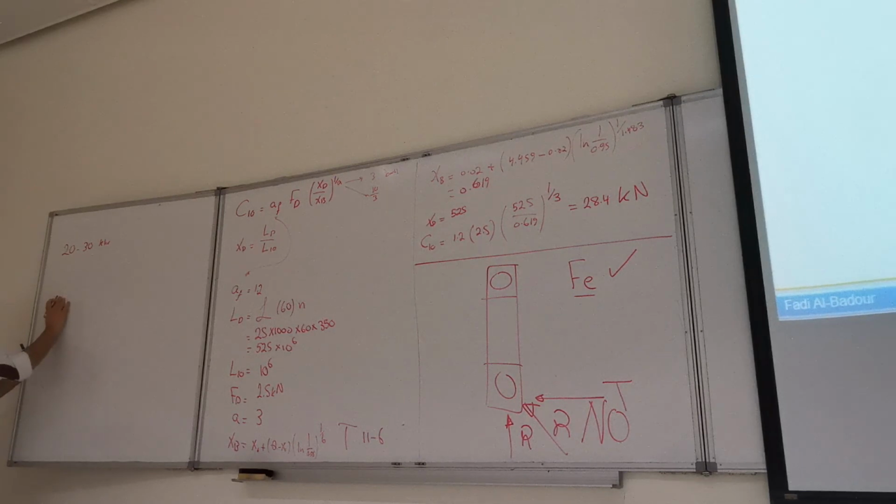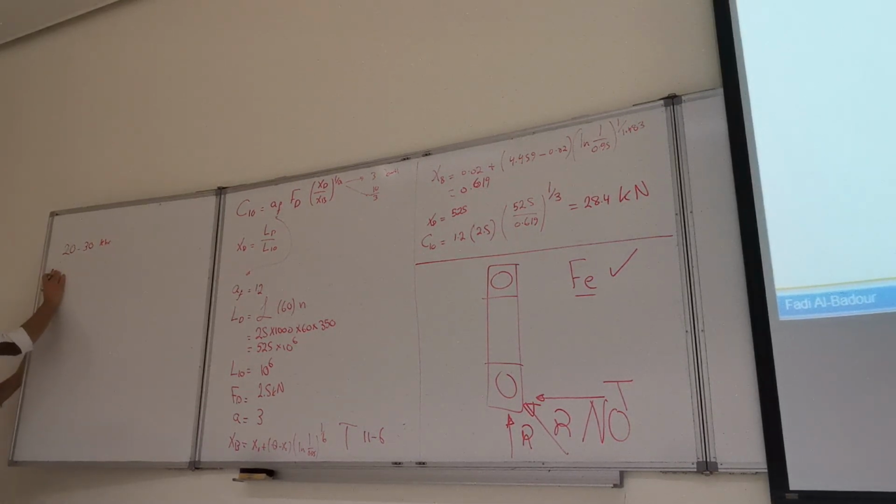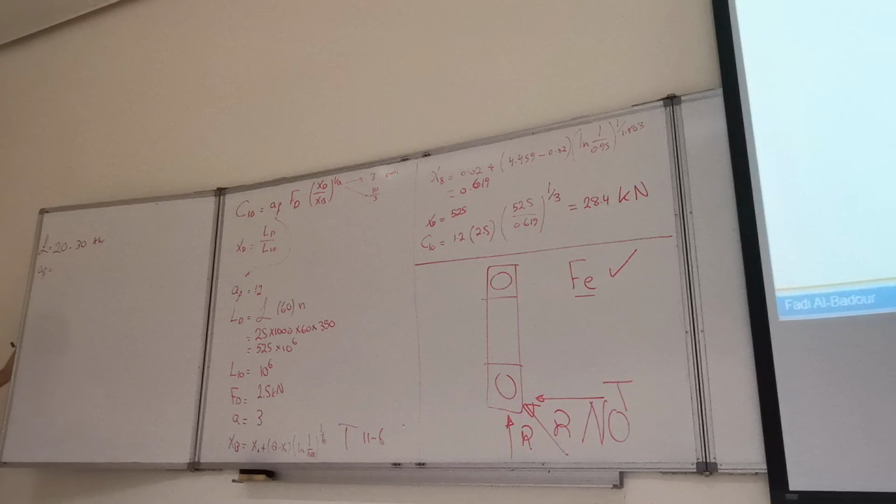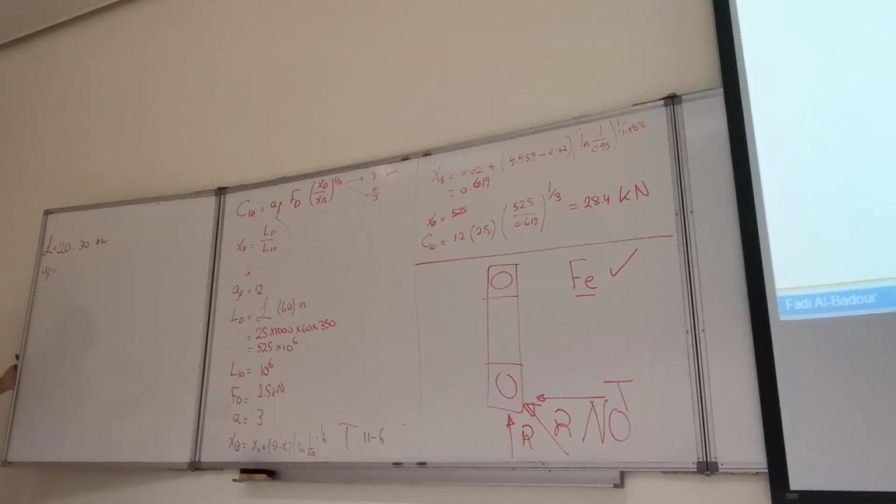So this is the range of operation. For the application factor, he said that the load is from light to moderate impact. If I go to the table, light impact loads have a factor from 1.2 to 1.5, moderate impact from 1.5 to 3. So if I'm between light and moderate, a suitable factor is 1.5.